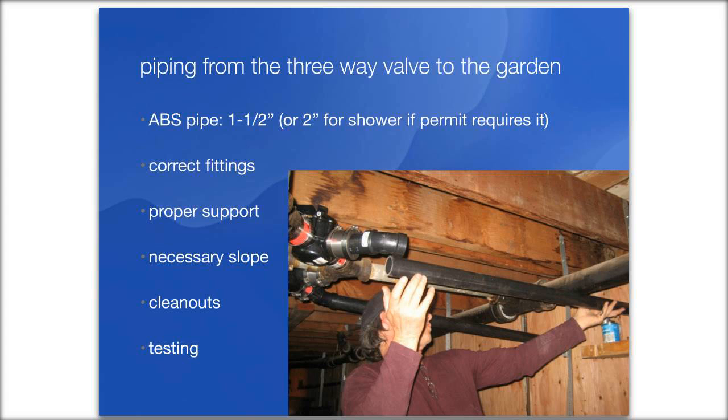So the last question was, if you're planning new construction with slab on grade construction, can the three-way valve go below the slab? Sure. New construction is often built slab on grade, so people want to put in a three-way valve when they're planning their new construction. So where should that valve go if their shower pipes are going to be in the slab? Wow, interesting. You would have to have an access panel somewhere in the floor where you could get to that three-way valve.